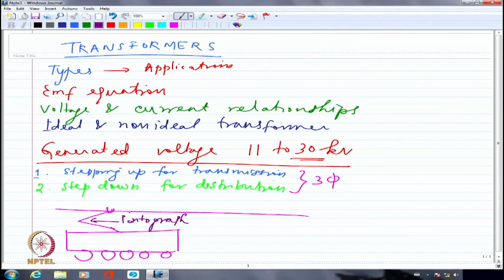So pantograph basically is a kind of a brush kind of arrangement, which is actually made up of a thick conducting material which is insulated by whatever is the insulator. They may have some plastic, bakelite and so on, and then that is having a U-shaped conductor which is sliding over the overhead transmission line to collect electricity. So this is the only conductor that is being used throughout the railway electrification zone. So this is the conductor or overhead conductor that we use.